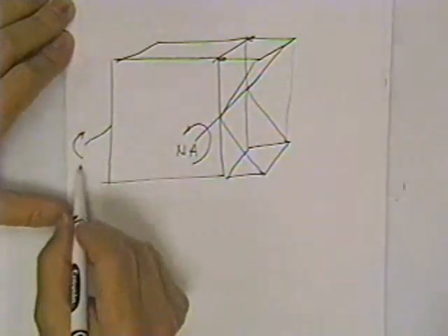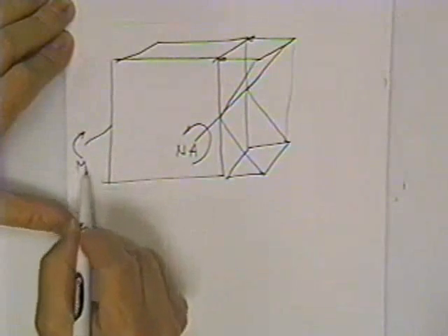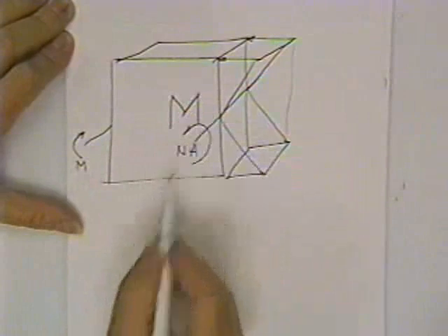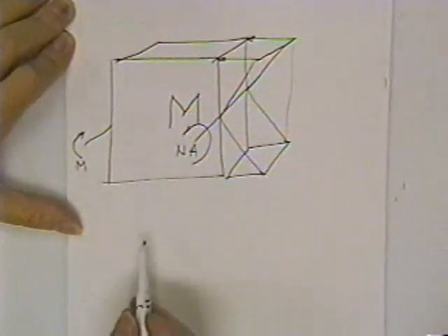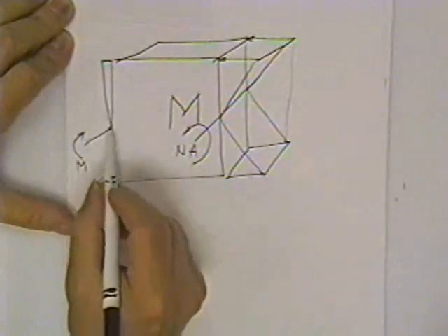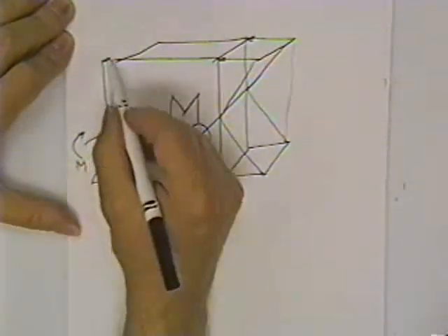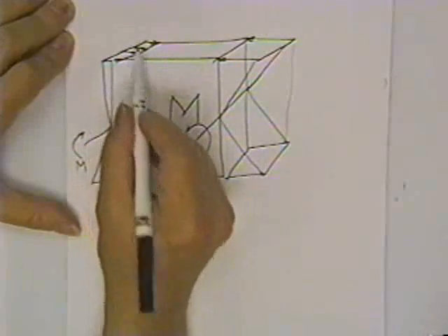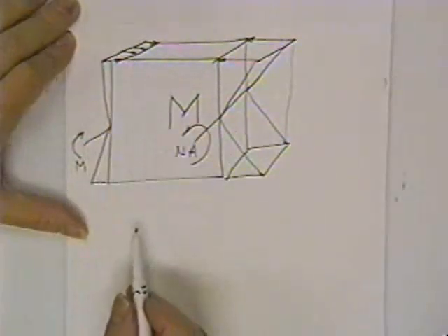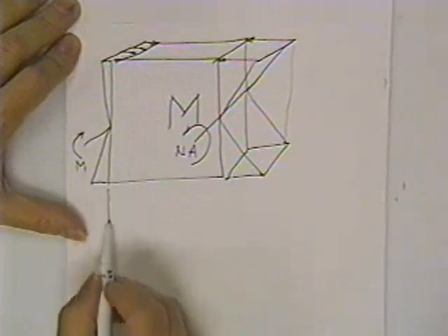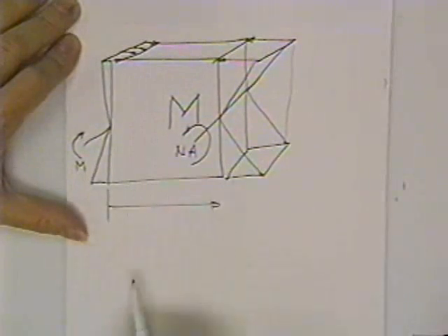Now, if the moment on this end is a little moment, and the moment on that end is a big moment, then the stresses on this side will not be as big, since the moment that caused those stresses is not as big. And that's okay. As you noticed earlier, many times the moment diagram changes value as you move across the beam.